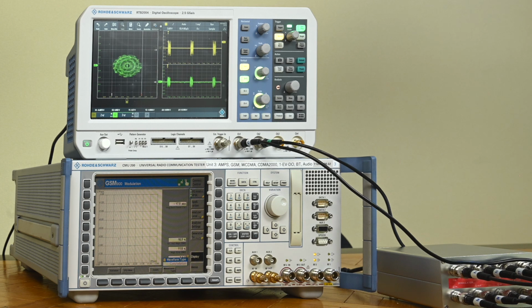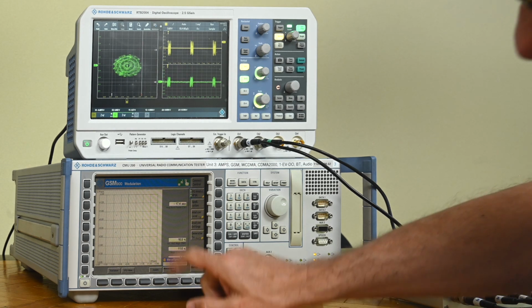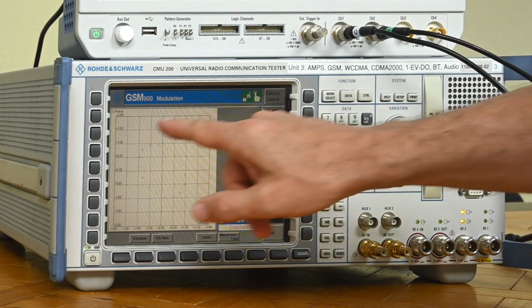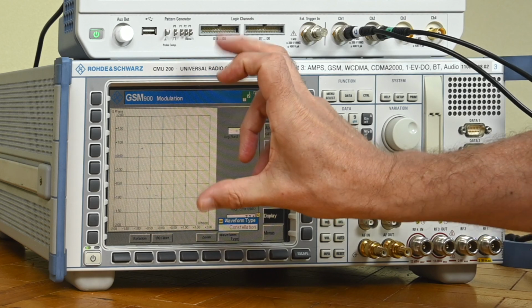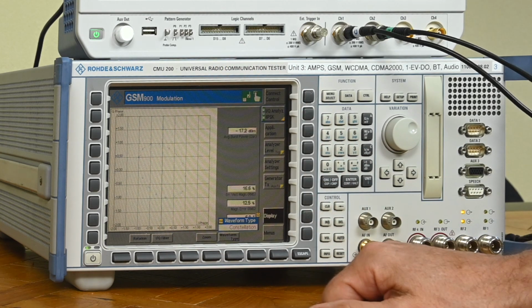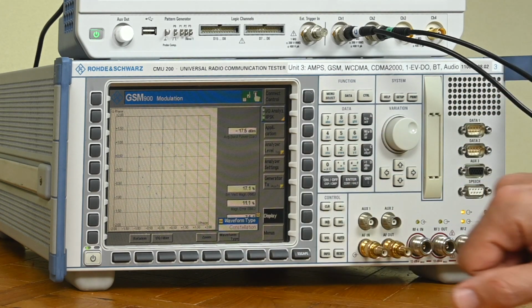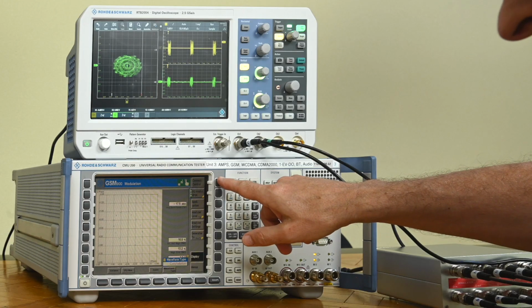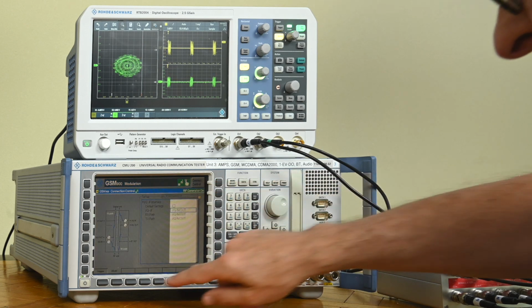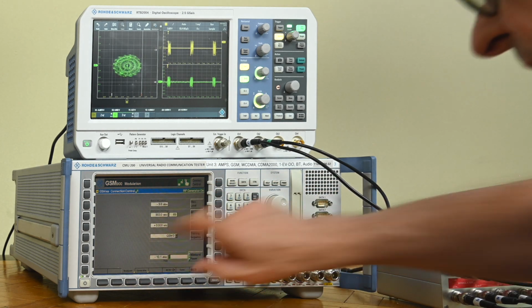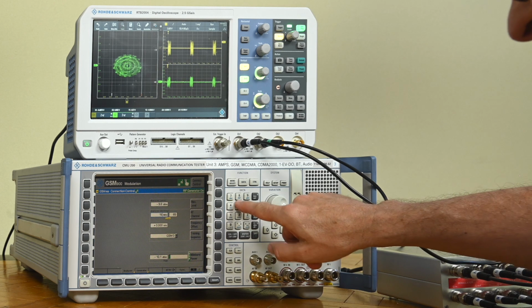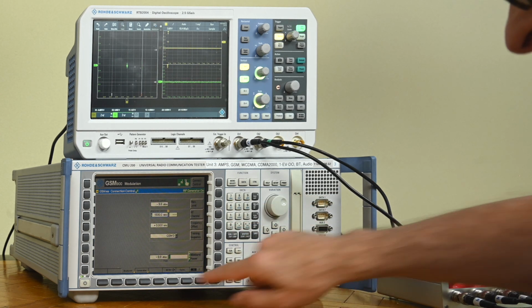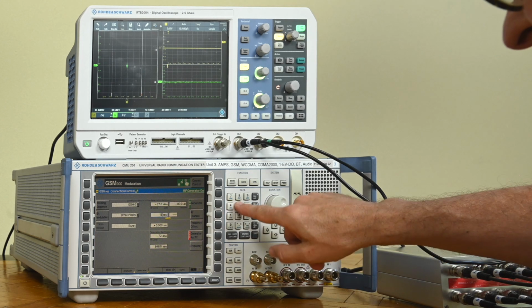There is another particularity going on here, and I hope I can show that to you. I would like you to remember that this circle has a bit of a distortion in one direction. Normally, because it's normalized, it already does that, but apparently there's still some distortion left. And the distortion is to the upper left. Do you see that? Now, what I'm going to do right now, and bear with me, is go to Connect Control and analyze. It's now at 900 megahertz, and I'm just going to do as if my transmitter is at 1500 megahertz and my generator is 1500 megahertz.